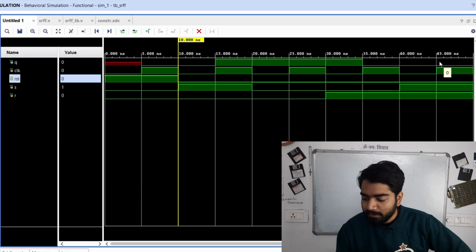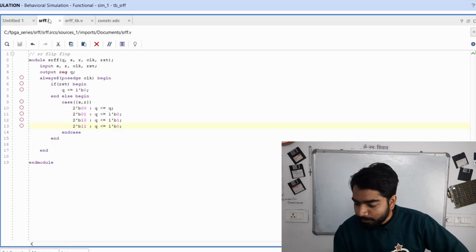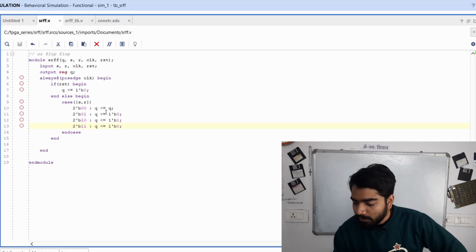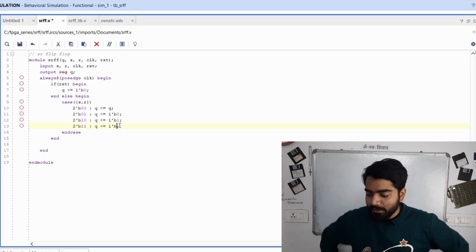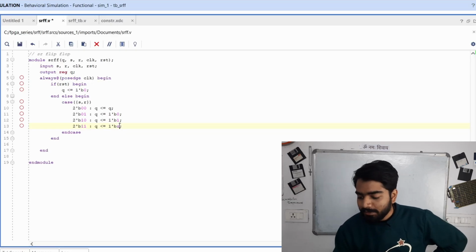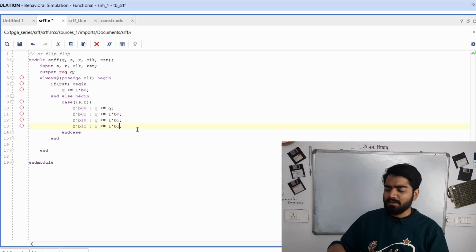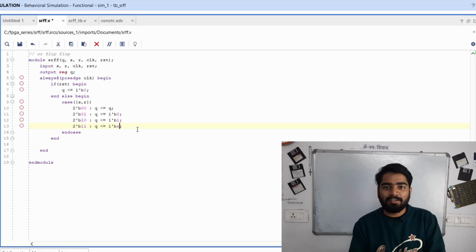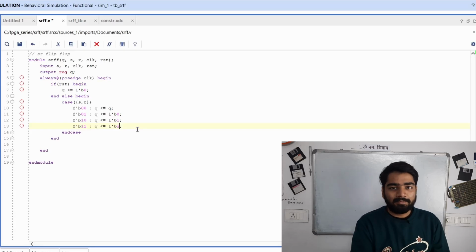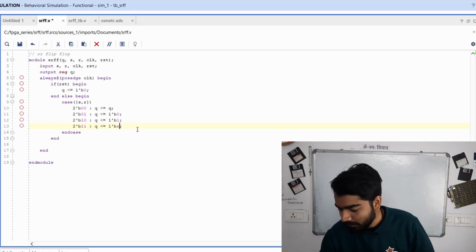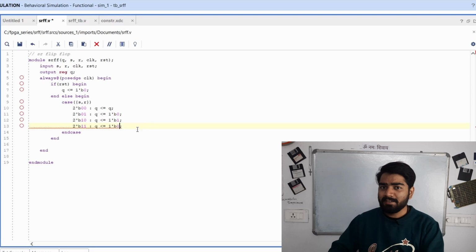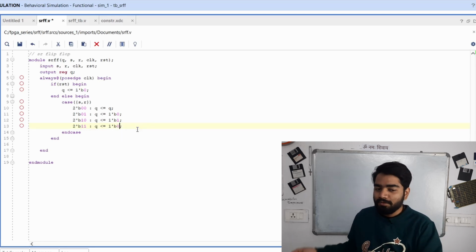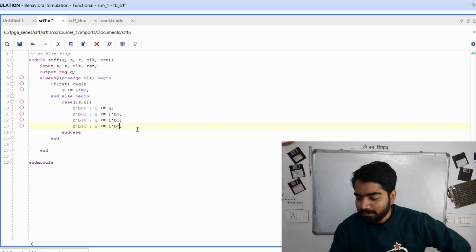So usually what they do in the SR flip-flop DUT code is assign 1'bz to represent that the output is invalid. But again, Z and X and all those things are not synthesizable on our FPGA. So we can use 0 or 1, anything, because it does not matter. Since it is an invalid case, the output doesn't really matter. Okay, so this is the SR flip-flop.